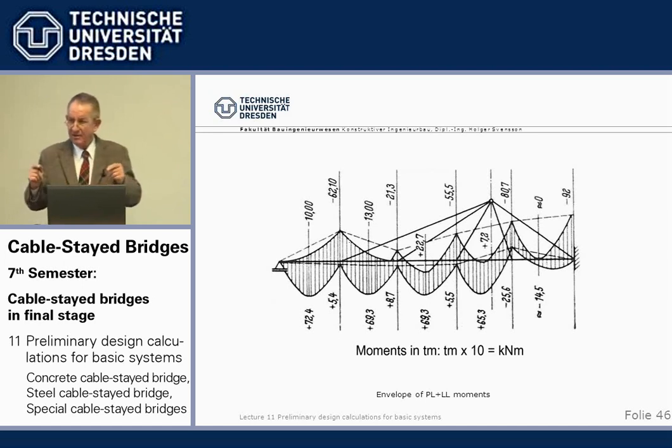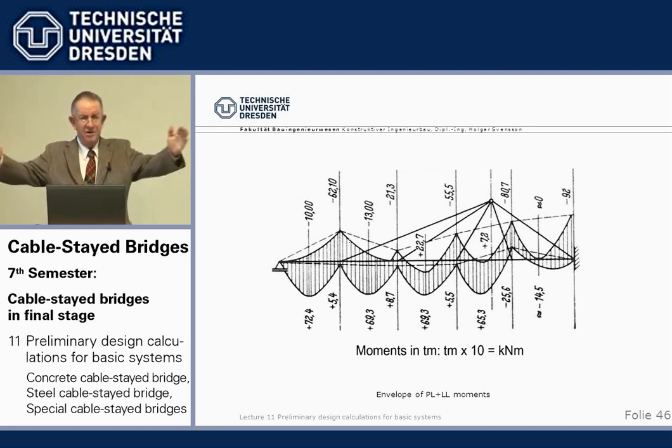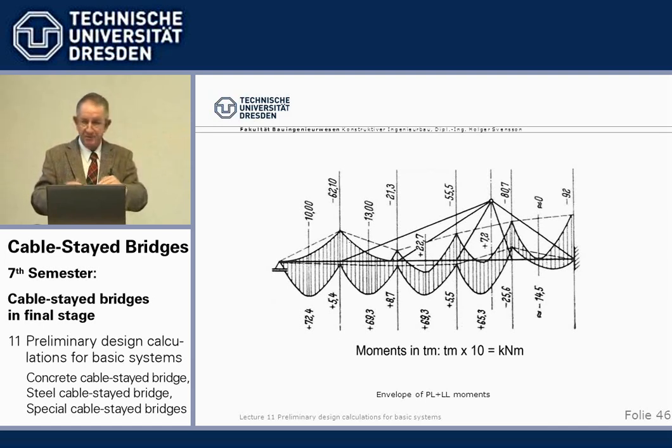Now, road bridges, of course, have a wide orthotropic deck, which has, for a minimum cross-section already, much more material in the top flange than in the bottom flange. The bottom flange just has the minimum required and is smaller.